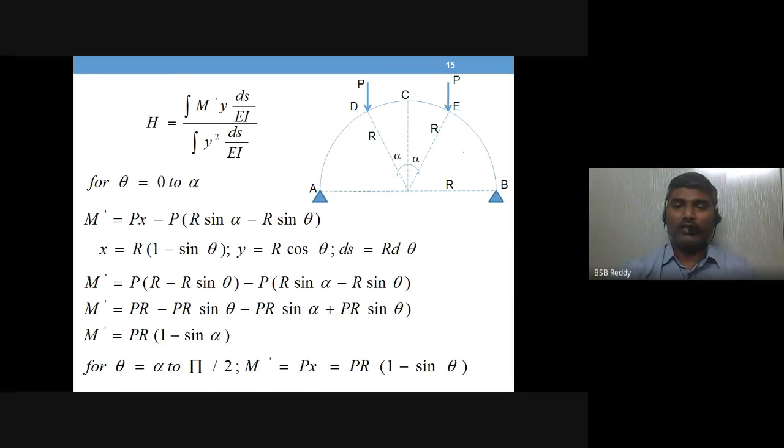Right. Now let us consider the arch with two loads, which is a modified diagram. For simplicity in solving, instead of writing three moment equations, we only need to write two equations: between AD one equation, between CD another equation, and it is the same to the right. Because it is symmetric, I can use twice the value. So that is the plan. Okay, this is the formula for h.